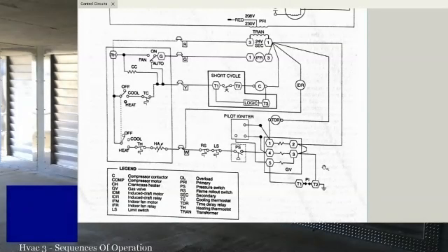Set the fan function switch to auto so that the indoor fan cycles on and off with the burners. So typically, if we're talking gas heat, the heat controls the fan operation, and it's usually at a different speed. Unlike cooling, where it sends power to G to operate that indoor fan relay, on a furnace, it's typically part of the control circuit. So the fan will come on automatically when the system wants it to, based on the sequence, usually at the very end after it's had time to heat up for just a second.